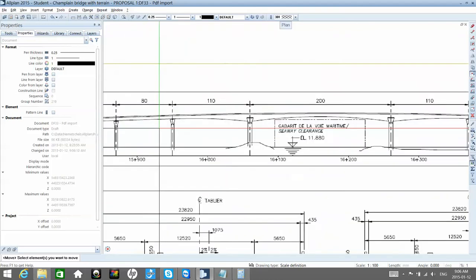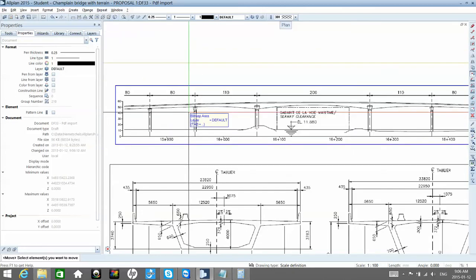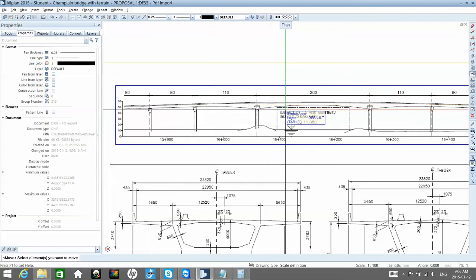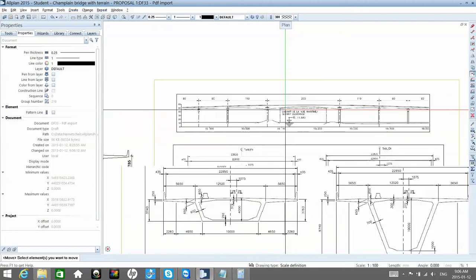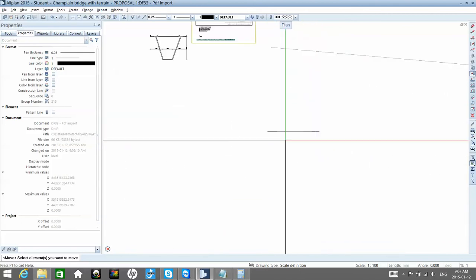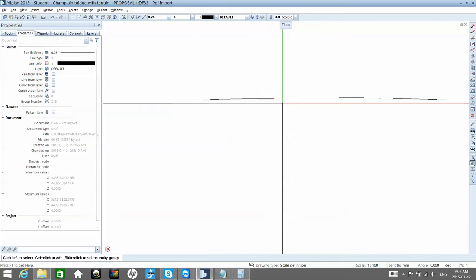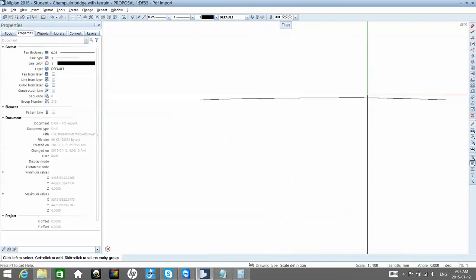This is a section through the bridge. The problem is the bridge is not straight. The bridge has some curves in plane, and this is the unfolding of the bridge that we see here. So the unfolding is longer than a projection in the plane. So we need to know the exact length of the bridge, and to make this longitudinal profile according to that real length. So this is why I measured that distance. This is how the bridge will vary in height, and the only thing I'll be doing now is a scaling on x coordinates.